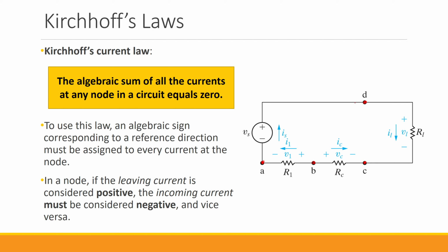So what does it mean? It means that, let's say I assume that I have a current called IM here. Also, let's assume I have a current coming in this direction called IN. If I sum the values of these 2 currents, considering their direction at this node, the result must be 0.